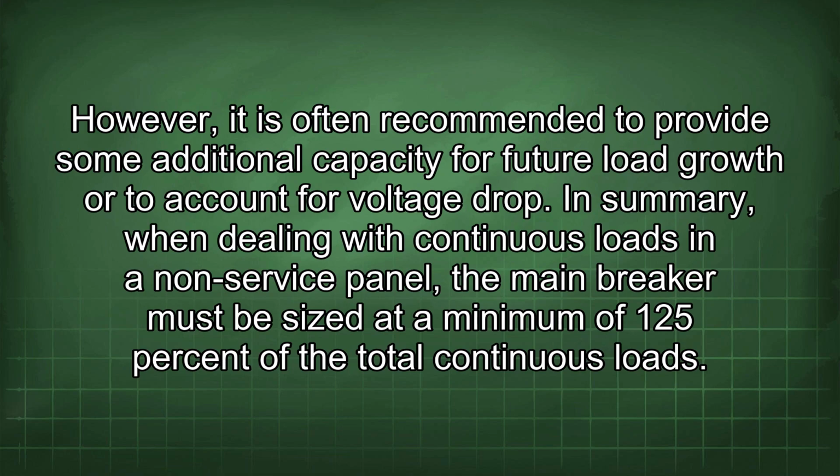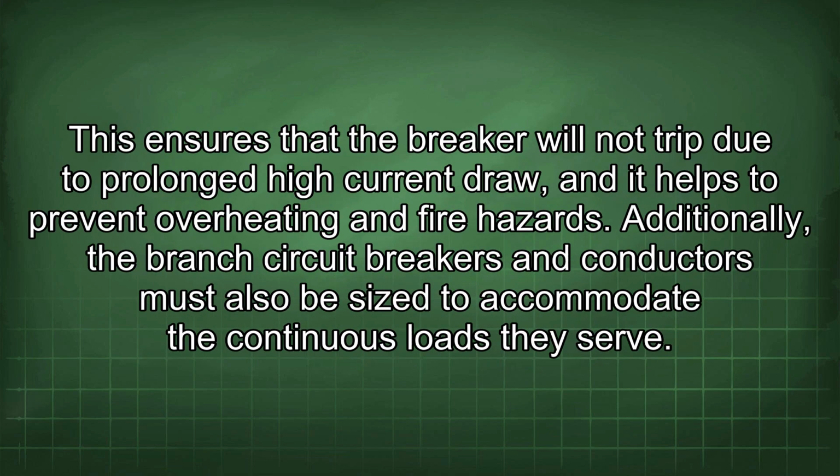However, it is often recommended to provide some additional capacity for future load growth or to account for voltage drop. In summary, when dealing with continuous loads in a non-service panel, the main breaker must be sized at a minimum of 125% of the total continuous loads. This ensures that the breaker will not trip due to prolonged high current draw, and it helps to prevent overheating